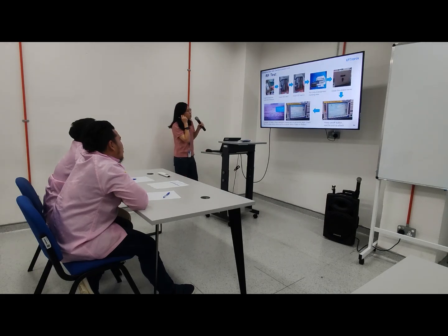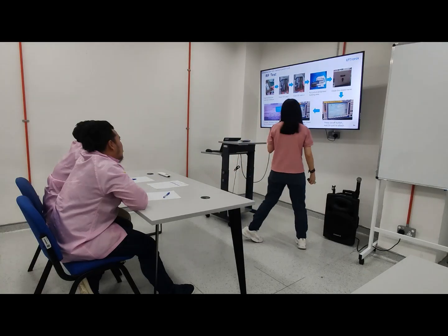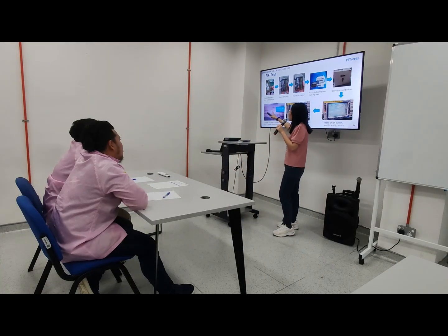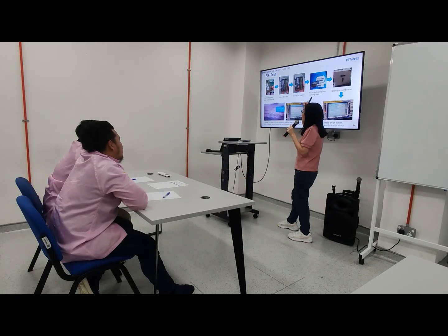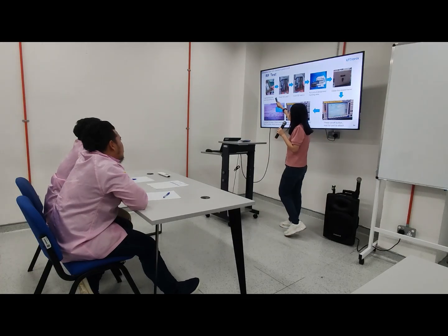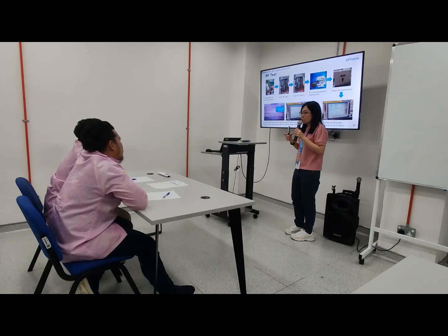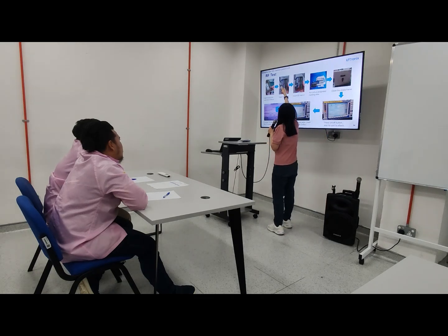Okay, last will be the RF test. For the RF test, I think there should be more steps compared with the previous tests. This one we need an empty SIM card. This is the empty SIM card. We need to change the original SIM card. We need to take out the unit's original SIM card, then we plug in the empty one. And then we also need the antenna.